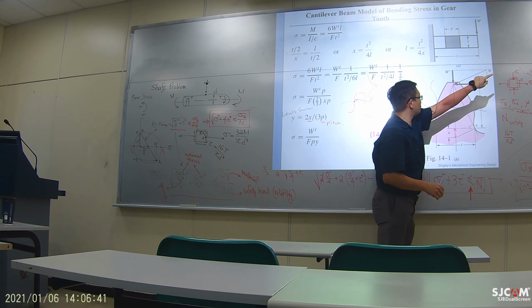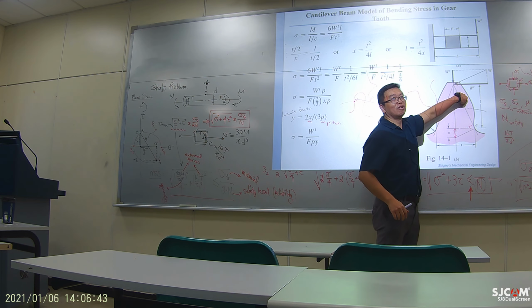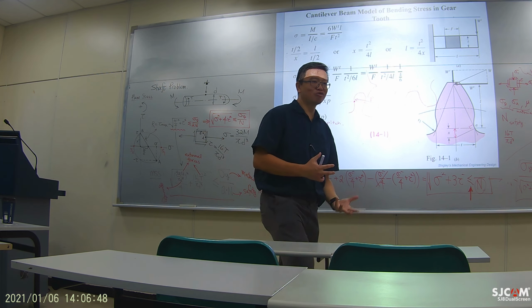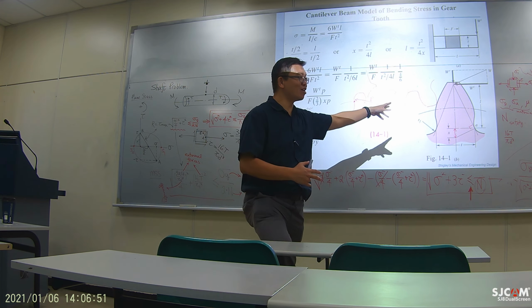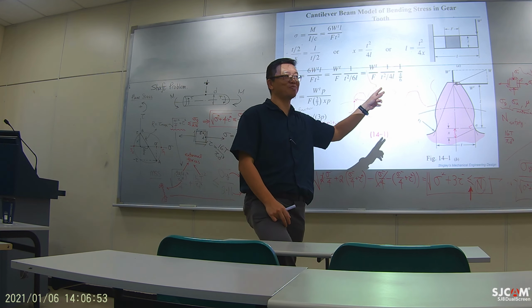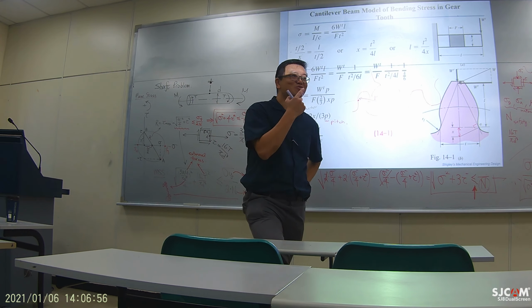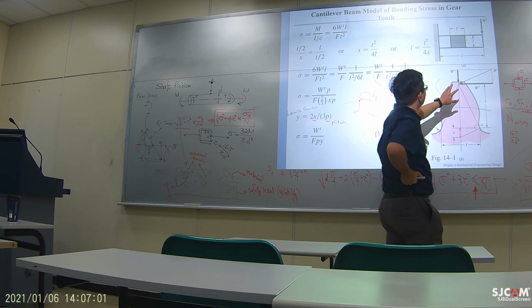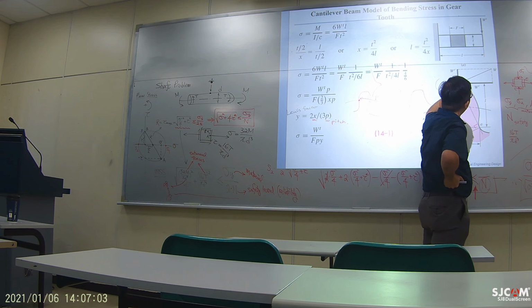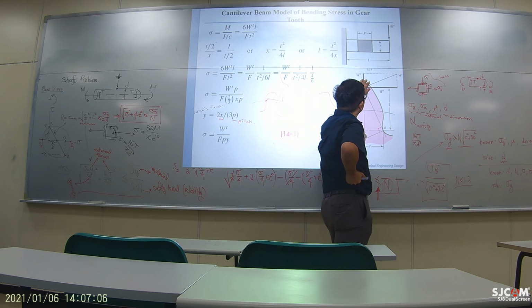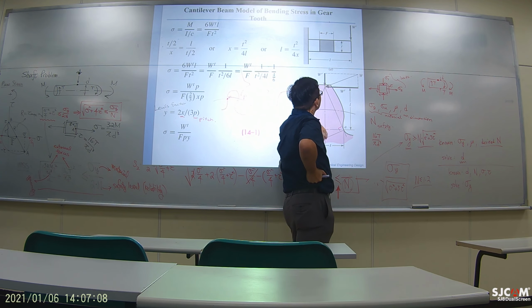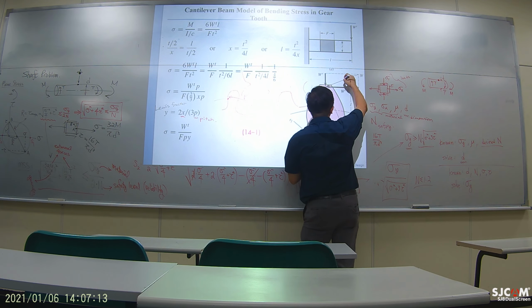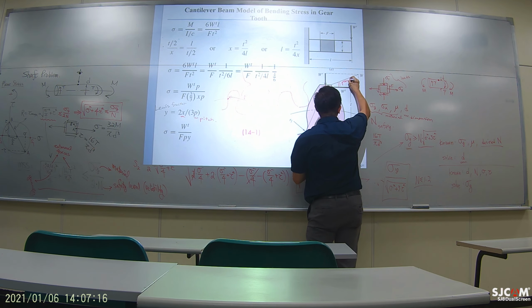There will be some other moment where the force comes at the middle, but that moment doesn't generate the most stress. So we only care about the most extreme one. That's why we only need to study this particular configuration. And how much force is going to be applied from here is related to the geometry of the tooth, and there will be this, which is like the pressure angle.